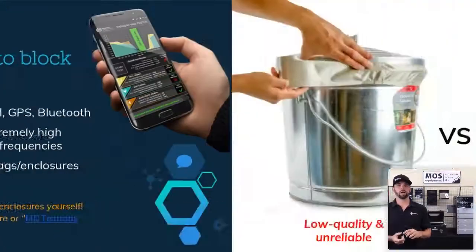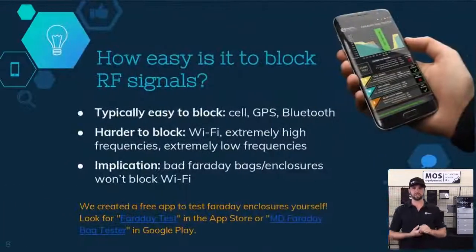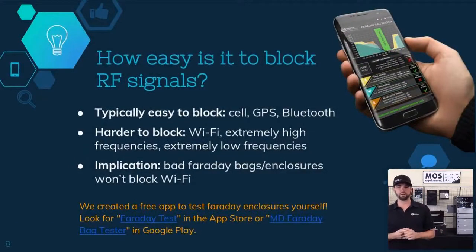All right, and then actually the second, let's go back really quick. Second implication of that is for testing. So for Faraday bags, whether you're buying ours or another company's, a good test, kind of a tip to make sure that it's still working properly, is to get it as close as you can to a router, whether that's like a home router, just a normal power one, or high powered if you can. Put the phone inside of it, get it near it, close it, and then use our apps, which there's links to on here, or just check the signal to make sure that it's blocking. And put it on 5G. That's kind of your best at home or in the lab test without a signal analyzer. Make sure that it's working. Next slide.